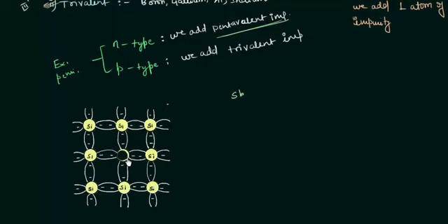Instead of this I will have antimony Sb, and as I have already told you, the antimony, the fifth group element, will have 5 electrons in its outermost shell. So 4 electrons will be combined with this, and this silicon atoms. 4 electrons are combined in this covalent bonds, and we still have 1 electron left. So I will represent this electron with a negative sign. This one is the fifth electron of the antimony.